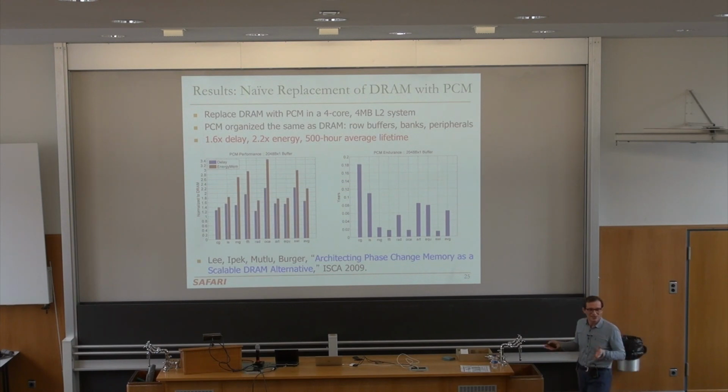Right? Basically, these applications write to memory reasonably often, and you can only do 10 to the 8 writes into memory. As a result, they basically eat your memory away as they keep writing. And that doesn't sound good also, right? You don't want a memory that gets destroyed after 500 hours. This is a real problem with flash, of course, but this is an even bigger problem if you actually put a memory like this on the memory bus.